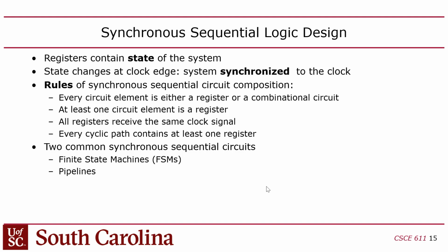Make sense? You might say, what do you mean? Software is always sequential. Now remember, SystemVerilog has concurrent semantics. If you write Verilog, everything in the Verilog code is happening at the same time. It's circuits that are concurrent. But what happens if you have some hardware operation that you have to break into phases? Then you have to use a state machine.